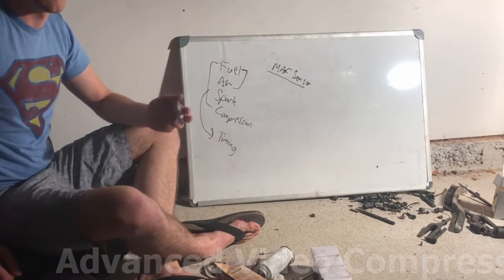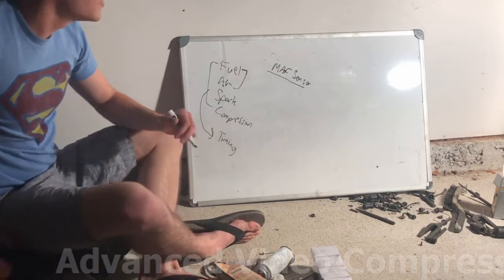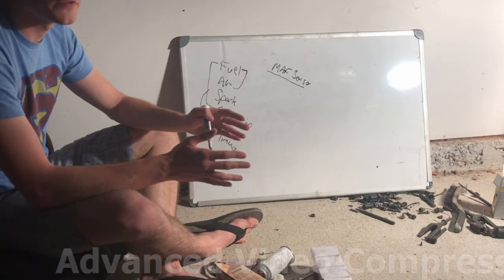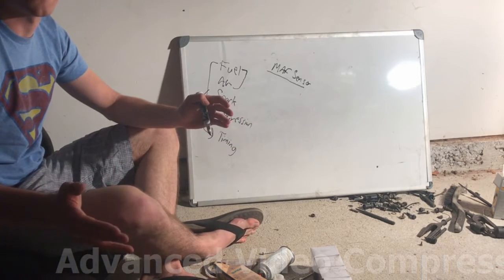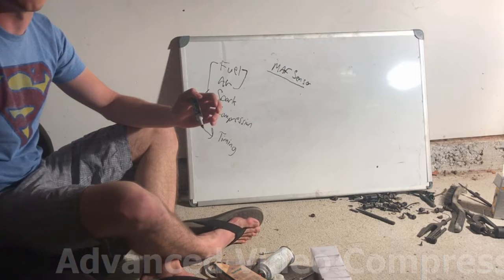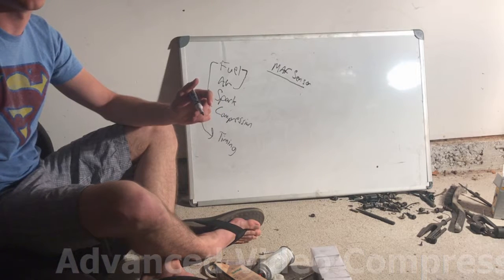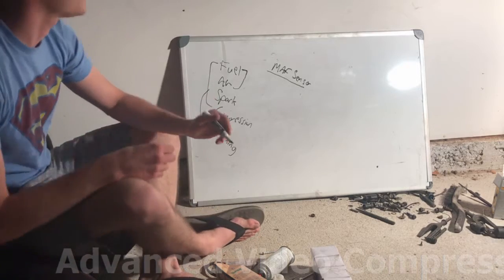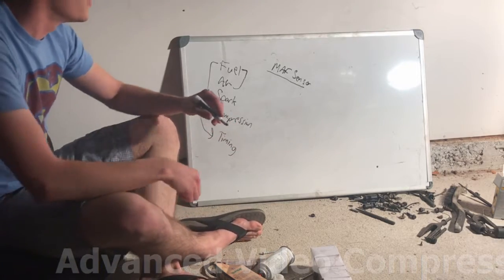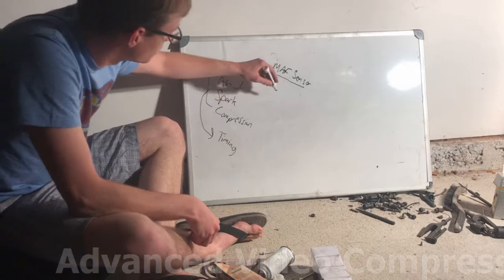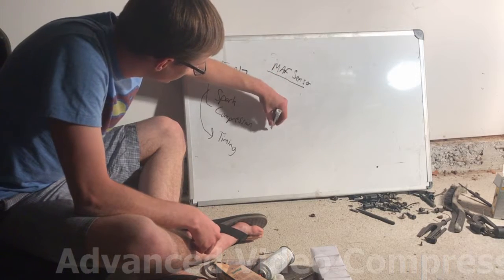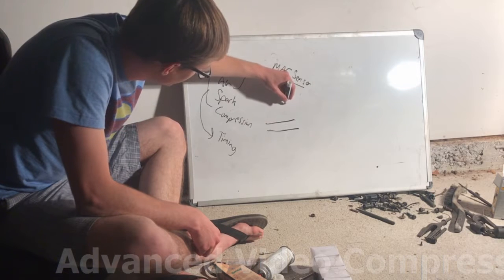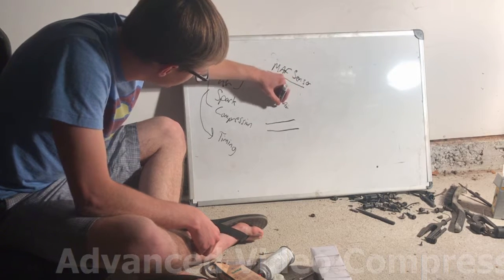So before I was talking about expected versus actual. What is the computer seeing? What is the actual value versus what is the computer expecting to see, i.e., what did the engineers determine were the expected values during testing inside the research and development facility? So here's our sensor, and basically the sensor is going to be housed on the intake side of the engine. So that's where air is coming in, air intake.